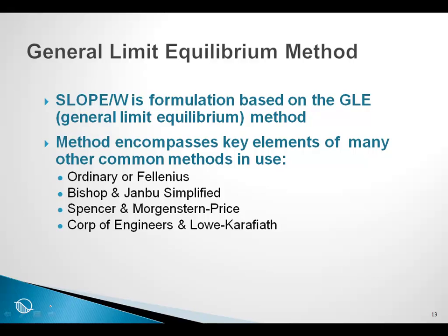SLOPE/W is formulated on the basis of the general limit equilibrium method. We call it the GLE method, and we will talk a lot about the GLE method in SLOPE/W. This method encompasses key elements of many of the other methods that are commonly found in the literature: the ordinary or Fellenius method, the Bishop or Janbu simplified method, Spencer and Morgenstern-Price methods, Corps of Engineers method, and even the Lowe-Karafiath method.